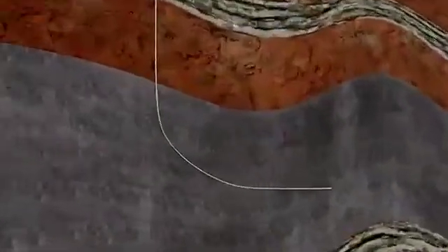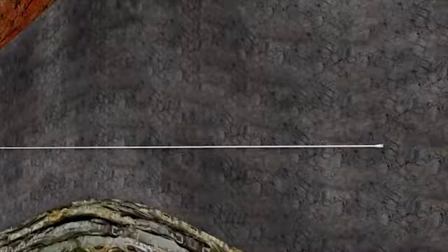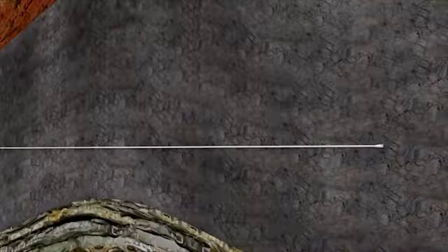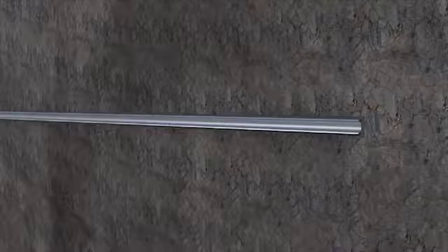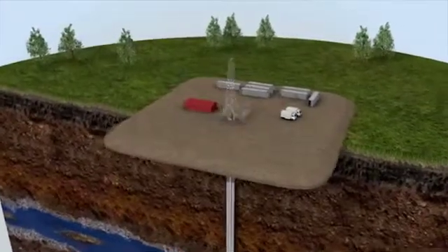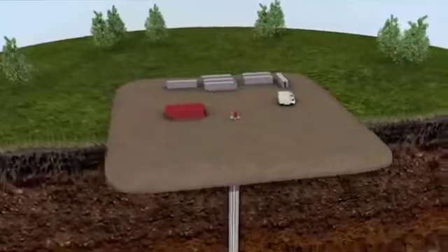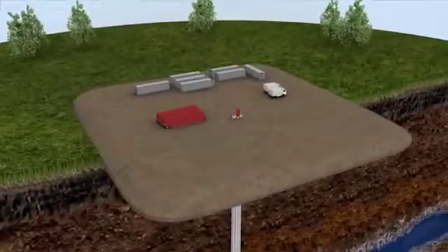One of the advantages of horizontal drilling is that it's possible to drill several wells from only one drilling pad, minimizing the impact to the surface environment. When the targeted distance is reached, the drill pipe is removed, and additional steel casing is inserted through the full length of the wellbore. Once again, the casing is cemented in place. For some horizontal developments, new technology in the form of sliding sleeves and mechanical isolation devices replace cement in the creation of isolations along the wellbore. Once the drilling is finished and the final casing has been installed, the drilling rig is removed, and preparations are made for the next steps, well completion.